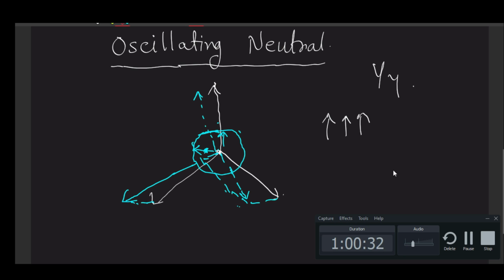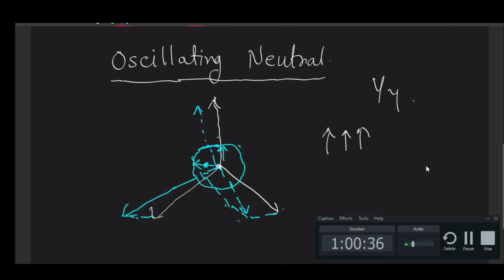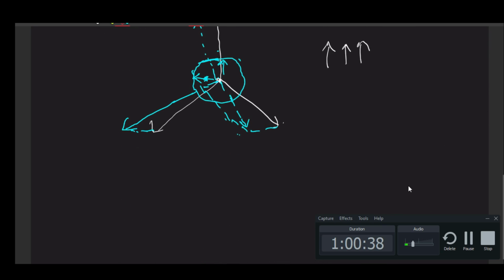That is not desirable, and that is why zero sequence is most alarming, because all these three are in phase. So now we will try to study the zero sequence component for different transformer configurations.